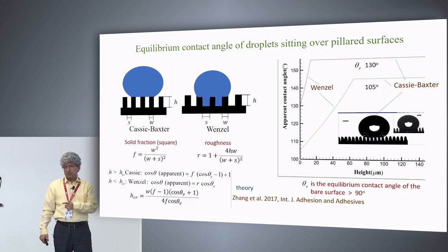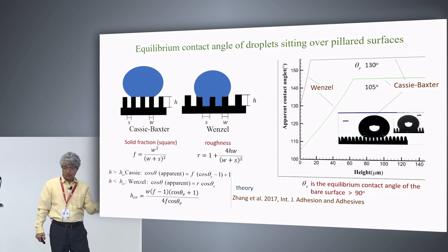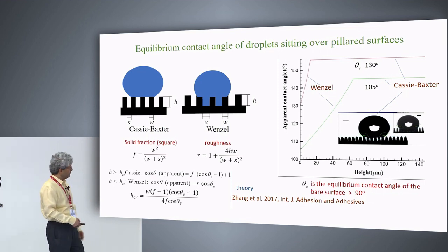From the condensation perspective, I said superhydrophobicity is to be preferred because then the largest drops formed during condensation are very small. The thermal resistance of the drop is small, cycle time is small, overall productivity goes up, water productivity.